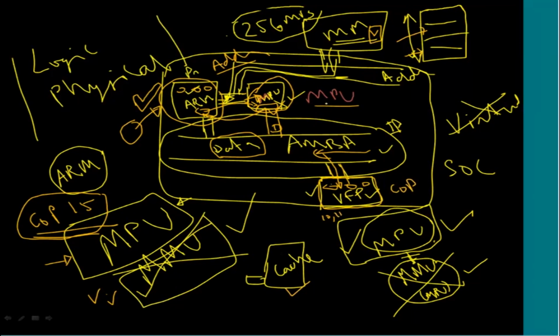So this MPU and MMU are connected to both address and data buses, and they may read the content based on which instruction is getting executed. If the ARM processor is executing a coprocessor instruction which is saying it is 15, then the MMU or MPU which is there in the system will become active and then try to understand what is being asked by ARM. So this is how the whole thing works in the case of MMU.